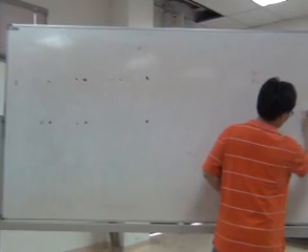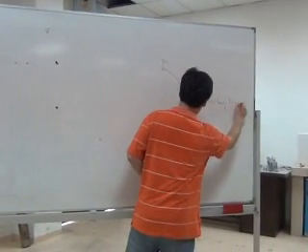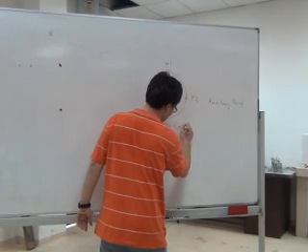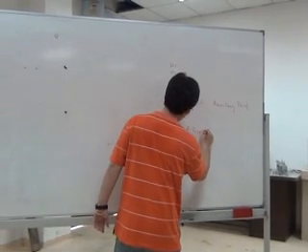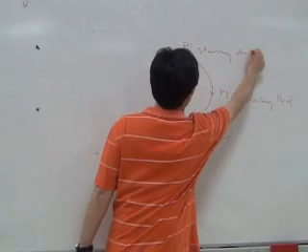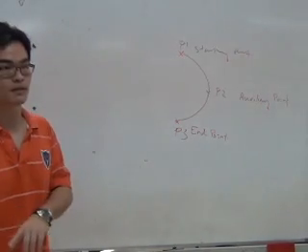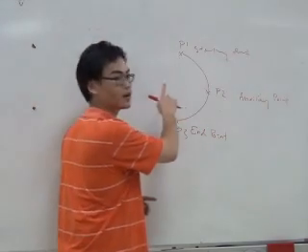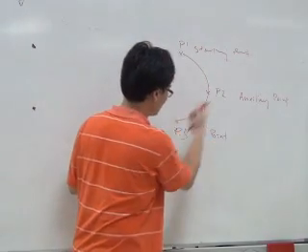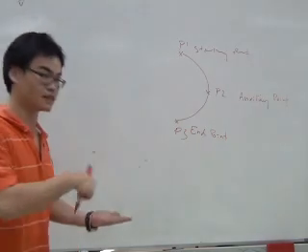This is what we call an auxiliary point. This starting point is the last point of the program. For example, now you have P2, right? So P2 will be your starting point. All you need is only one more auxiliary point and one more point. And this is fine when you're drawing a circle on a flat surface.